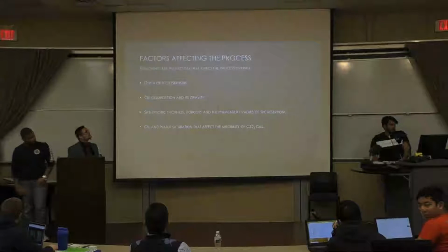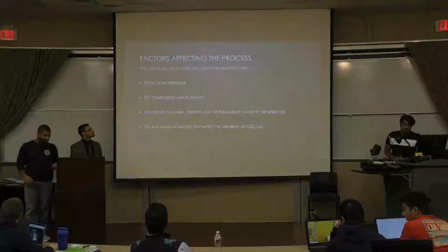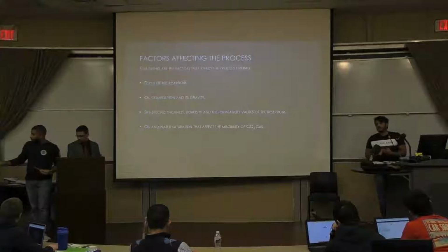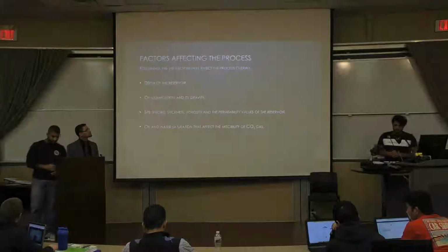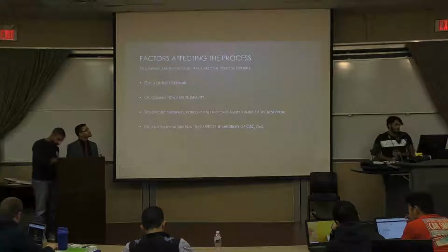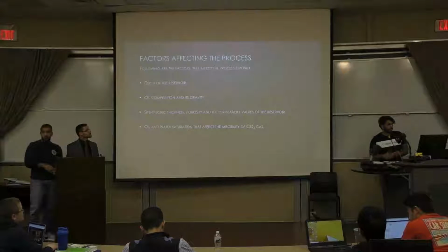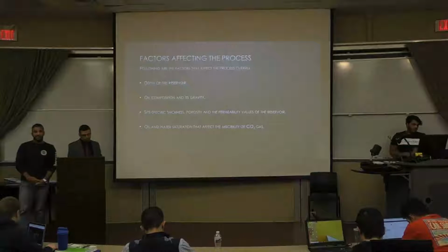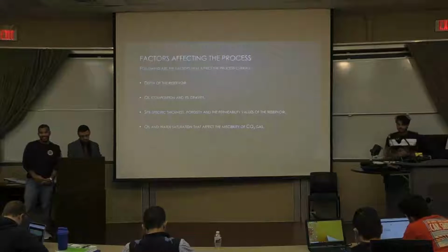There are some factors affecting this process, like the depth of the reservoir, affecting the temperature and pressure, and hence the physical characteristics of the CO2 gas. And the other ones are oil composition and its gravity, site-specific thickness, porosity, and the permeability value of the reservoir, and oil and water saturation, which affect the miscibility of CO2 gas.